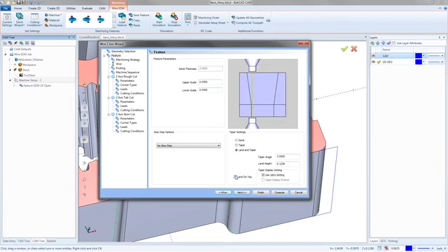And then how this actually displays is normally what you'll see when we compute this is you'll see just a straight cut, but it doesn't show you the full straight cut all the way down. So you see just the top half where you get the straight, and then you'll get a taper, but it doesn't show you the wire kind of taper. So if you go in and you say taper display extend, this is going to switch it so that whenever we do a land and taper, the land that we see, so this area here, if we leave the taper display on and this one off,